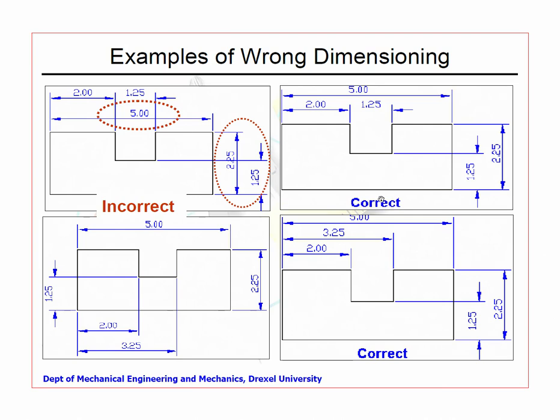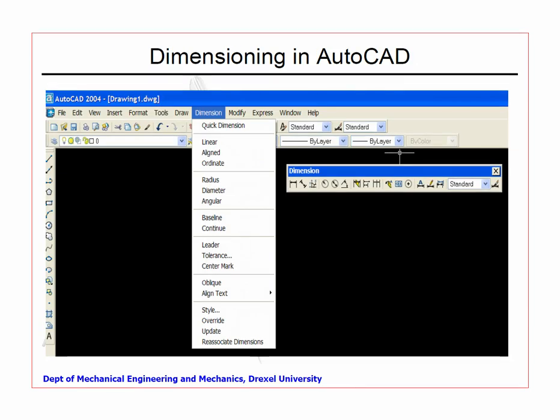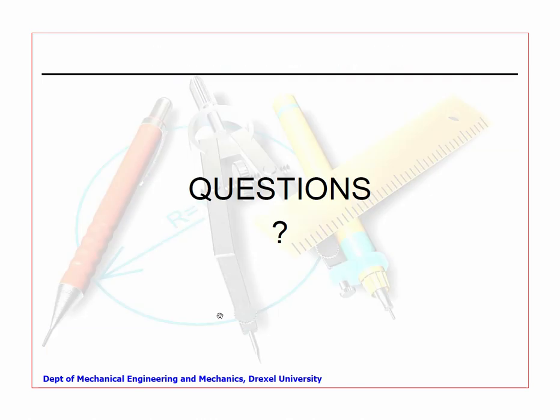two variants here, the groove width is given here and the starting point is given. In this case, from a datum line the things are shown here. So, both are correct, and logically if you place everything one after the other it will be easier to understand. In this case 2.25 has been given here and 1.25 has been taken there. While in principle this is correct, it leads to confusion. Same part if you have to be dimensioned like this, it will be very convenient for us to do these things. Do not worry too much about it, whichever package you have, usually these are common in this.